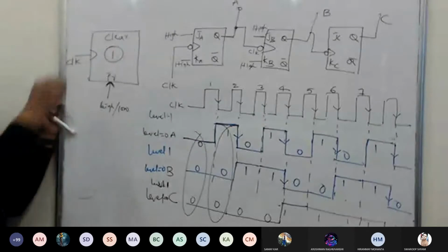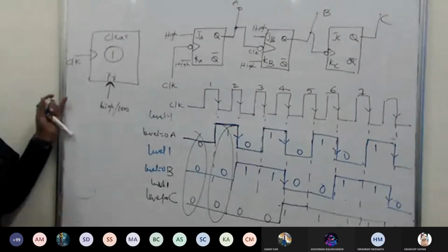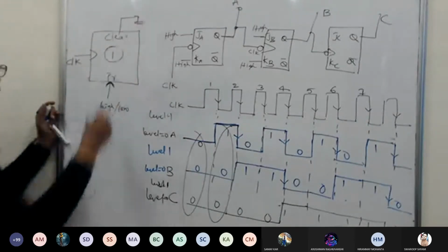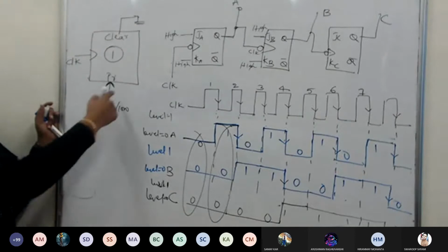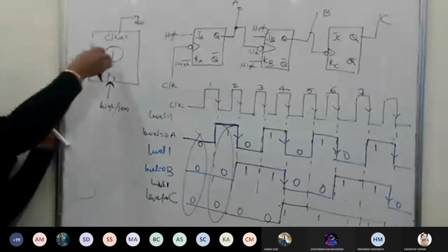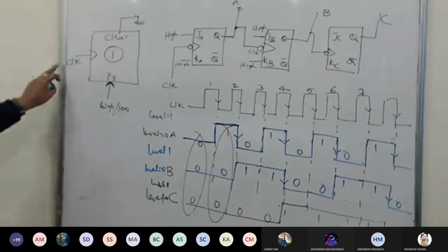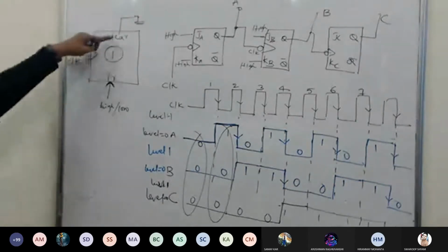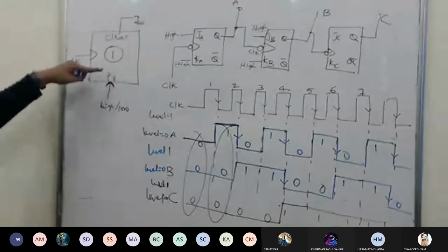Okay, now all of a sudden I want to clear it. Clear means I can use this pin and put it to ground. I can ground it. So what is happening? Whatever you have loaded in the preset will be shot out. That means again it becomes empty. Please try to understand. Loading it, getting it emptied. Loading it, getting it emptied. So who has the more major power? Earlier we had only the clock as the major one, right? No, not necessarily the clock. Clock will have an understanding only when these two work properly.